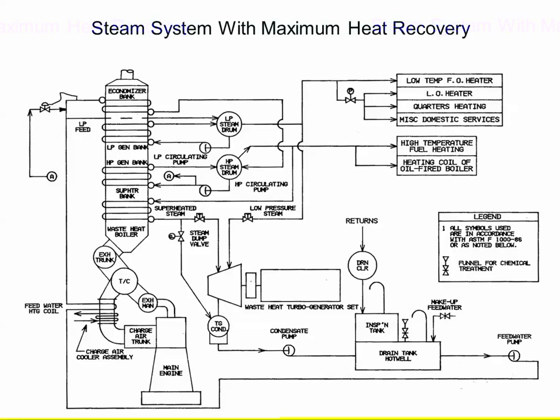So again, just as a quick review on a combined cycle, one of the more high efficiency ones out there. To get that high efficiency, you may have a low pressure and high pressure system. That's so I have two different saturation temperature relationships, which will increase my delta T, and I can pick up a little more heat. I can have a steam turbine that would use any heat above what I need for just heating services, in a combined cycle to produce power for the plant.